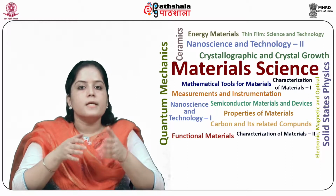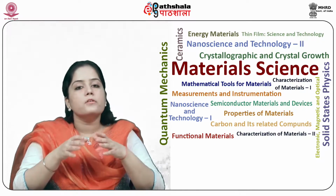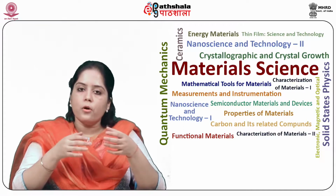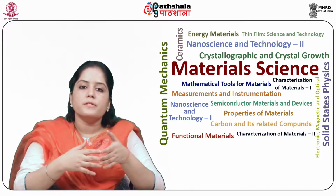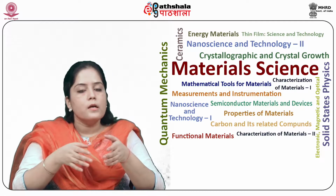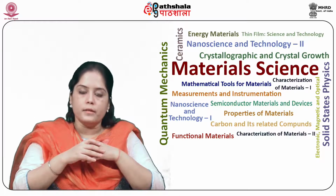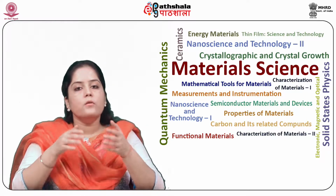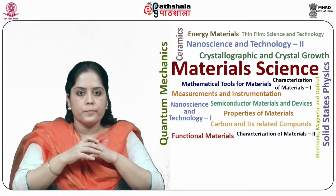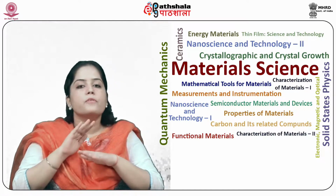So, thermal oxidation is carried out at 1100 degrees Celsius plus or minus 10 degrees Celsius in 100% oxygen ambient. The wet oxidation of silicon was performed for 10 hours by passing water vapors with oxygen gas. Dry oxidation is carried out initially for 30 minutes, followed by 10 hours of wet oxidation, and again dry oxidation for 30 minutes. The residual water molecules from the wafer surface were removed during dry oxidation. It may be noted that the SiO2 film is growing on both sides of the silicon wafer.